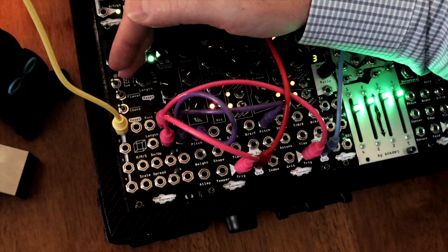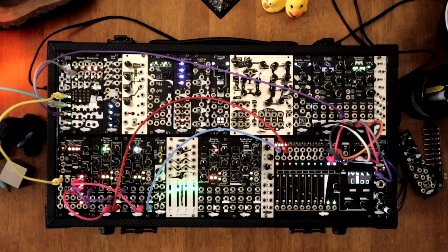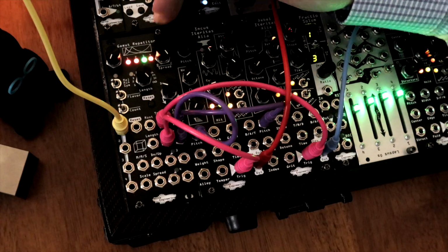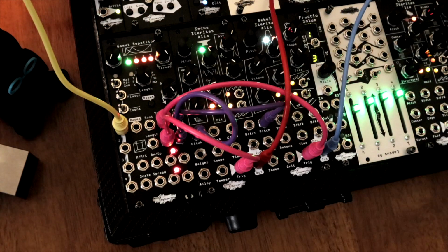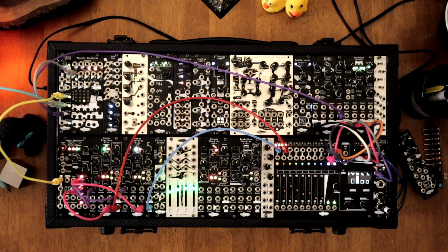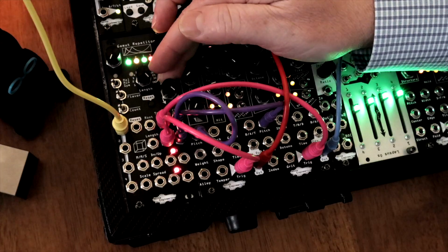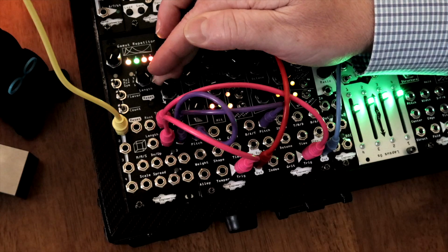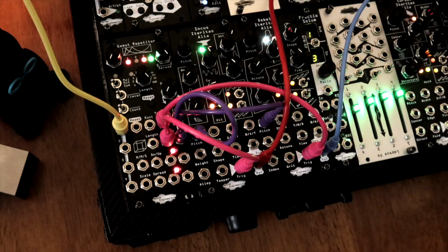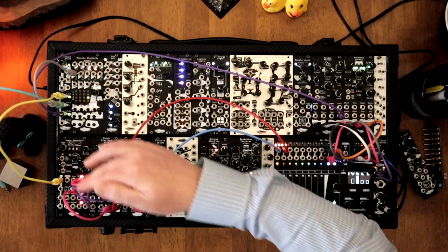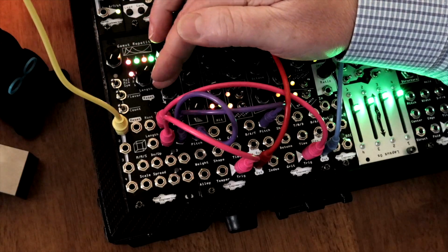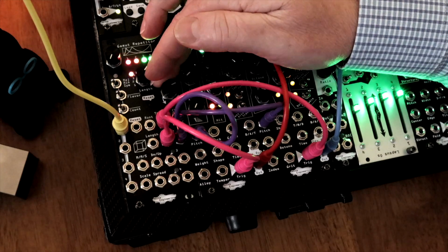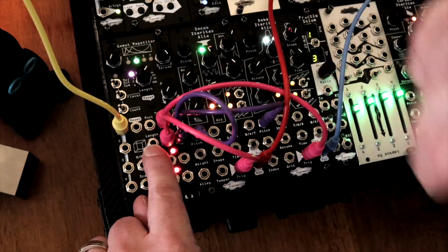The down-up parameter shifts the range of the voltages around the root note. For example, if spread is set to 2 octaves and down-up is set all the way up, the highest voltage generated would be 2 octaves from the root, and the lowest would be the root. If down-up is set to the left, the highest voltage would be the root, and the lowest would be 2 octaves below it. You can randomize this pattern by adjusting the note, spread, or down-up parameters by hand or through their CV inputs.